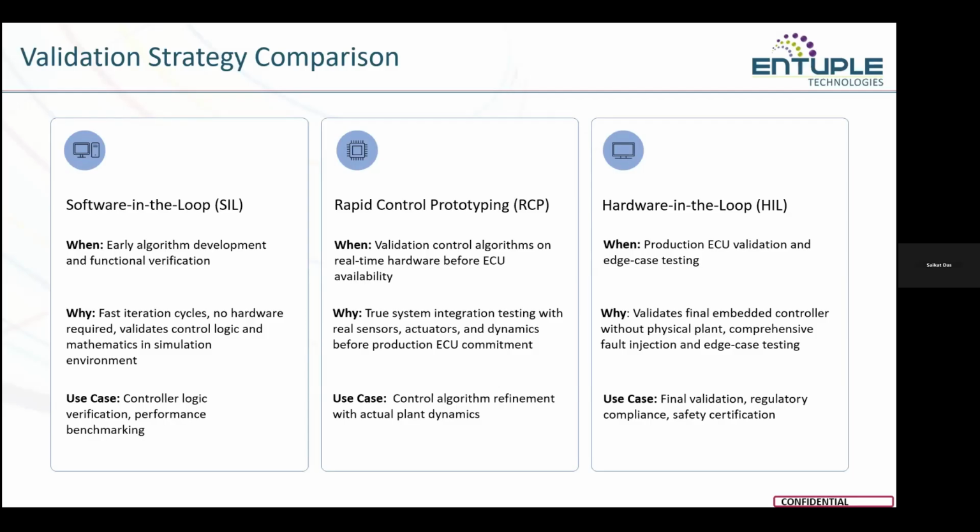Yeah. So HIL allows safe testing of edge case and fault conditions, failure scenarios that are difficult as well as unsafe to test on real hardware. If you want to test those scenarios in a unit, we have to use hardware-in-the-loop systems. So this stage is essential for final validations, regulatory compliance, and safety certifications.